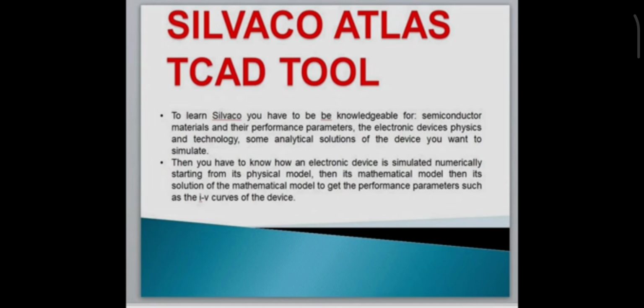SILVACO TCAD tool. To learn SILVACO, you have to be knowledgeable about semiconductor materials and their performance parameters, electron device physics and technology, and some analytical solutions of the device you want to simulate. Then you have to know how an electron device is simulated numerically, starting from its physical model, then its mathematical model, then the solution of the mathematical model to get performance parameters such as the IV curve of the device, and finally the post-processing of the computational result.